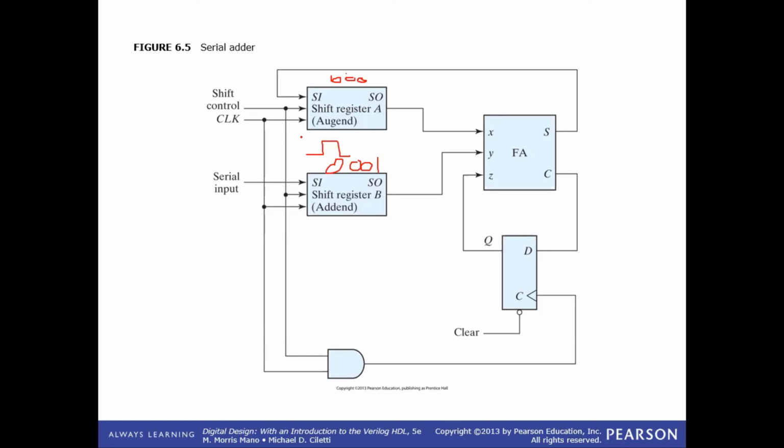So at each positive edge of the clock, the least significant bits, that is this 0 and this 1, would move to the cleared full adder. The cleared full adder means at the start, the full adder would have been reset. So a 0 would reach at the X, a 1 would reach at the Y, and since there was no carry from behind the circuit, we'll have no carry at the output at the start, so we'll have 0. Now I want any one of you to explain what's going to happen next.